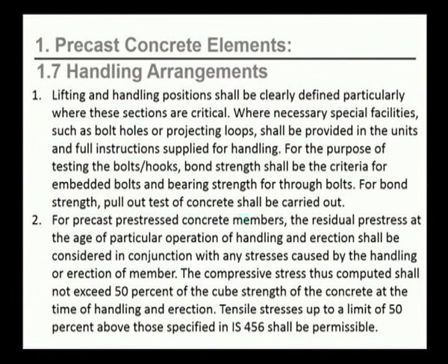Lifting and handling positions shall be clearly defined, particularly where these sections are critical. Where necessary, special facilities such as bolt holes or projecting loops shall be provided in the units and full instructions supplied for handling. For the purpose of testing the bolts, hooks, bond strength shall be the criteria for embedded bolts and bearing strength for through bolts. For bond strength, pull-out test of concrete shall be carried out.